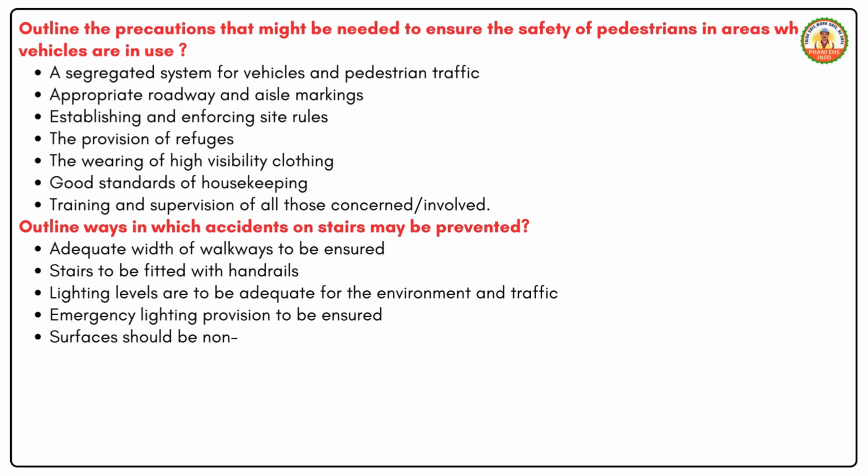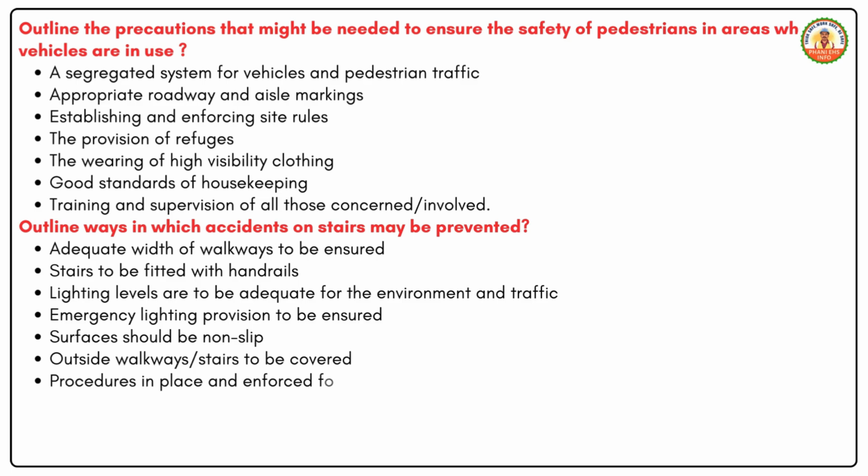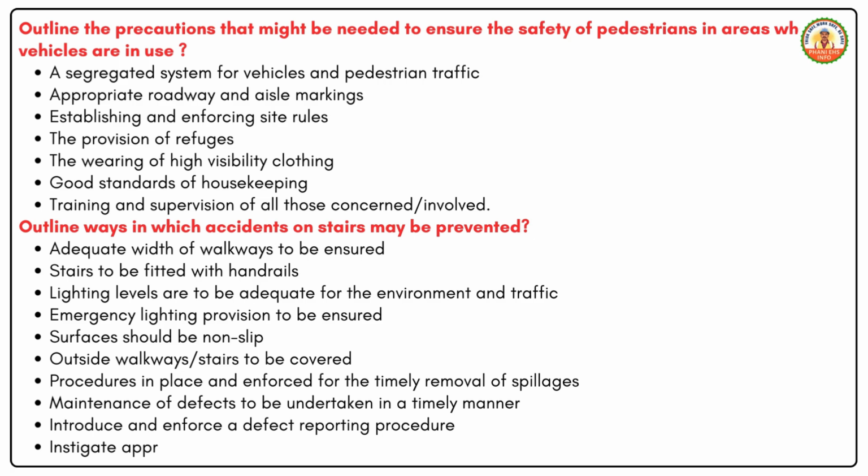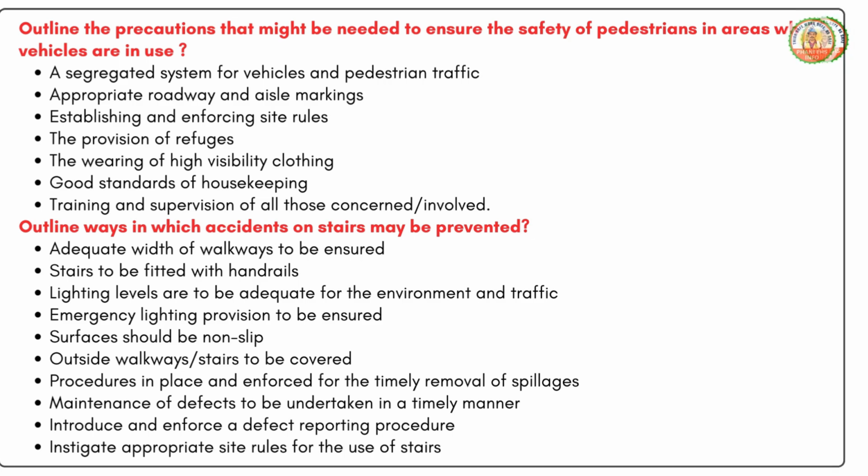Surfaces should be non-slip. Outside walkways and stairs to be covered. Procedures in place and enforced for the timely removal of spillages. Maintenance of defects to be undertaken in a timely manner. Introduce and enforce a defect reporting procedure. Instigate appropriate site rules for the use of stairs.